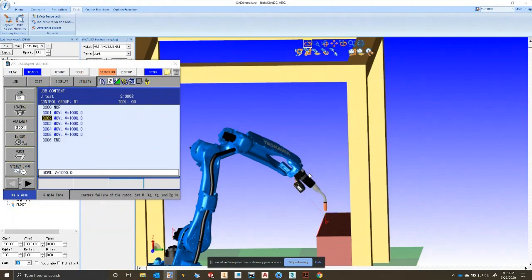Right. Wayne asks, can you optimize speed and cycle time based on tool data? Oh, yes. Very much so. I've seen 9-10 second savings sometimes. I actually had a demo. We're running out of time, but it only shaved about 1 second off the configuration I had, so it wasn't that dramatic. I do have a simulation somewhere where the cycle time was about 20 seconds, and when I put the right tool data in, it dropped down to 9 seconds. So yes, tool data is very important for cycle time.